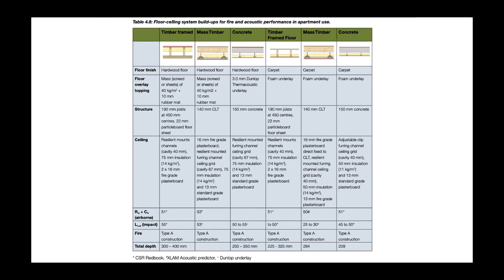So this table's presented there, and it gives you the fire performance and the acoustic performance of both the timber and the concrete solutions to allow you to reference back to what would be the developer's benchmark in many cases, which is to say concrete flat slab. So you can say, look, concrete flat slab performs in this way. We've got an equivalent performance from this timber solution of this depth. Therefore, in my design, I need to use this mass.